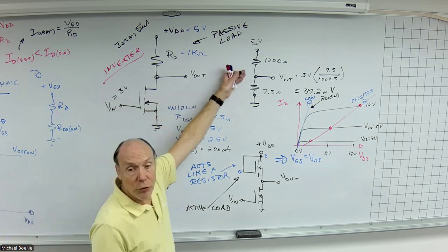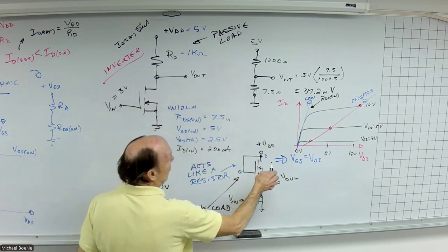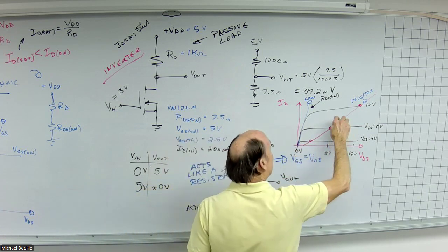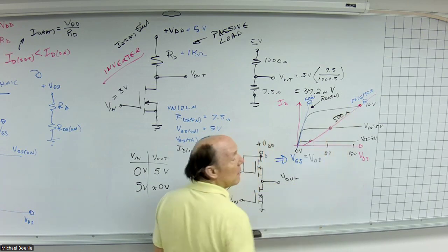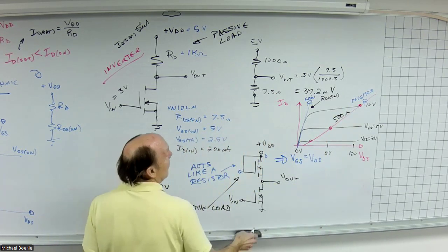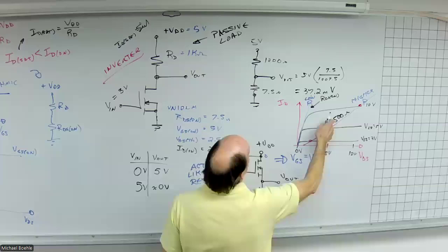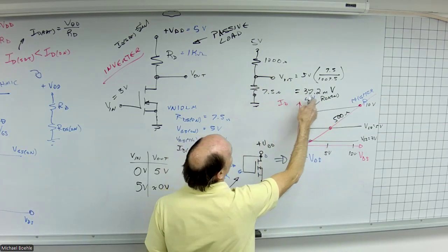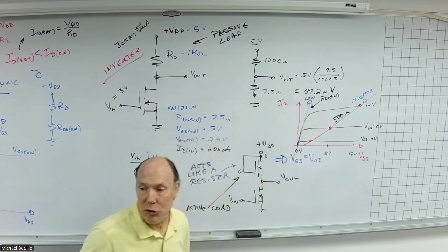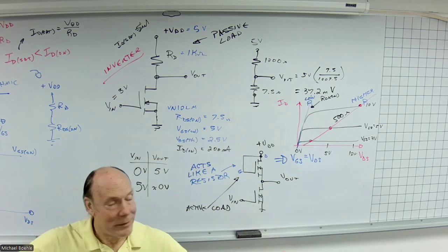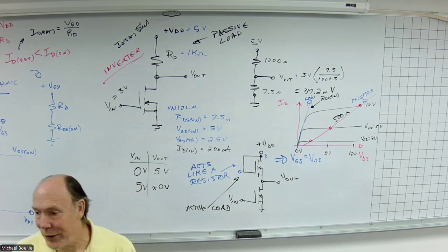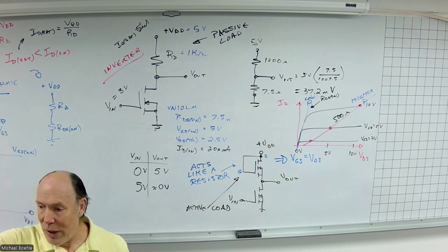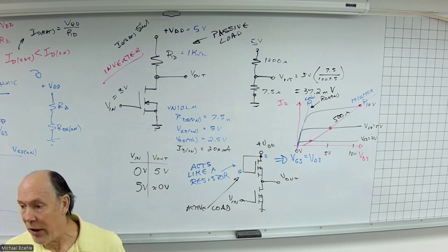And I still get that same switching characteristics. I still get the same voltage division. Let's say maybe as an effective resistance, it acts like 500 ohms. Well, fine. So now, because this went from 1,000 to 500, and this is still 7.5 ohms, ooh, I roughly doubled that voltage. Now it's all the way up to 75 millivolts. Still very close to zero, still a lot less than the gate source threshold voltage.